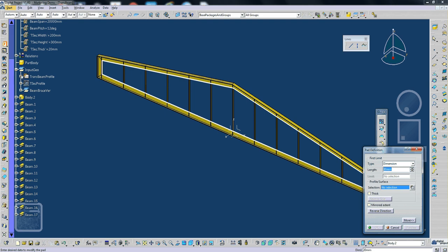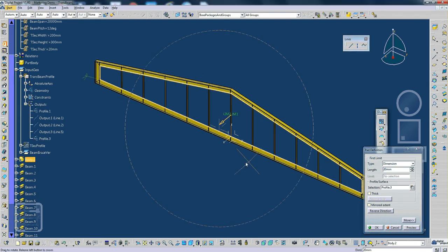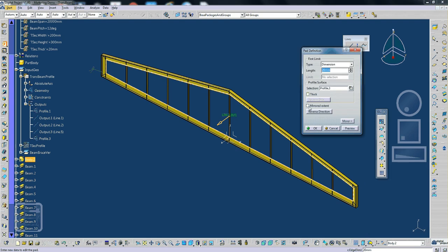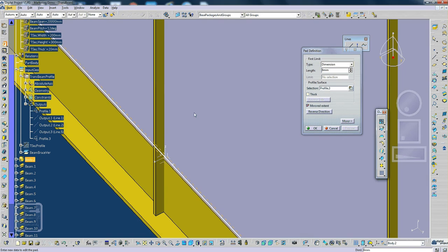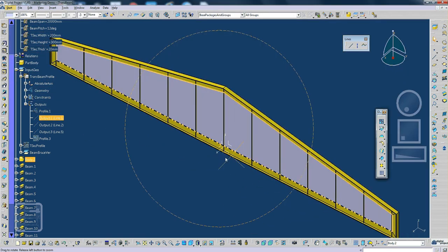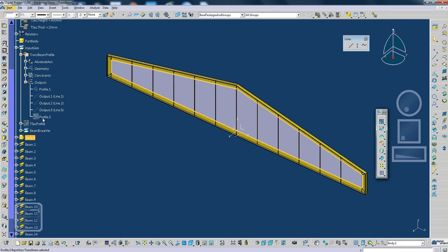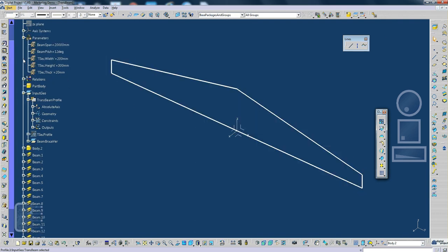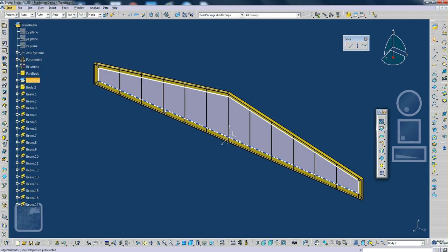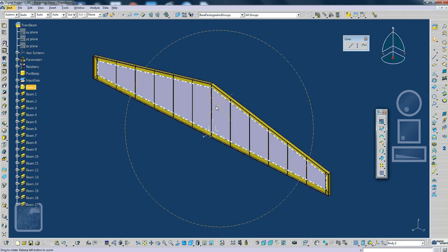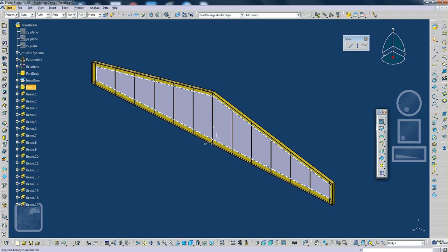I will use the profile from this sketch, profile 3, and I will click mirror extend, give a depth of 10. Just check. Let's zoom in, make it 8. Preview. Okay, so we've got this plate. Okay, it's done. Right. So this file is ready to be inserted into a product file later as one completed beam, transversal beam.